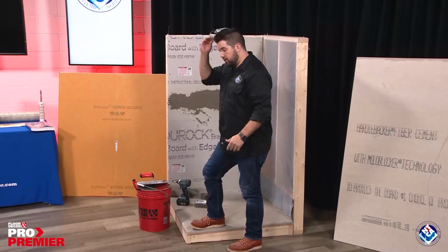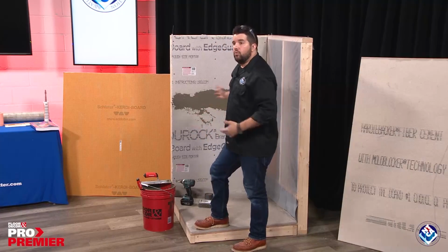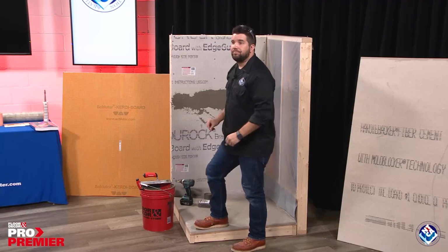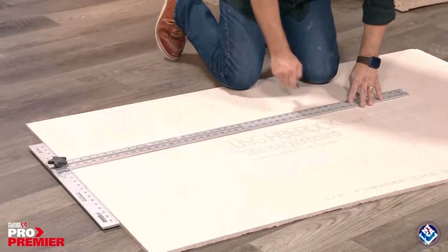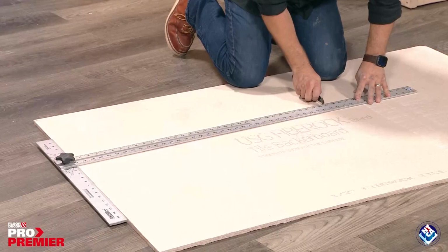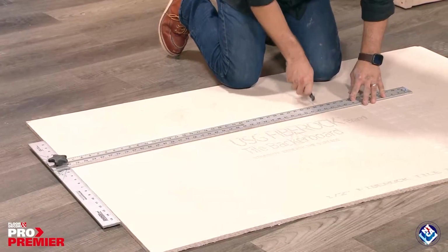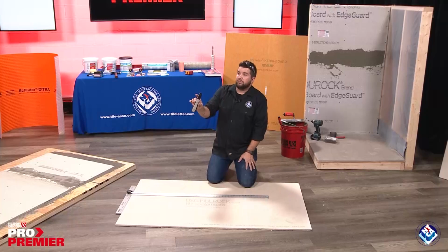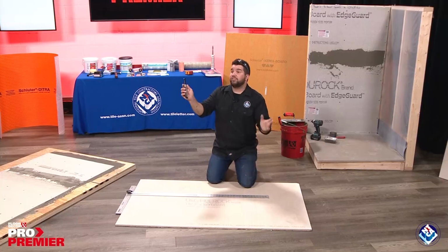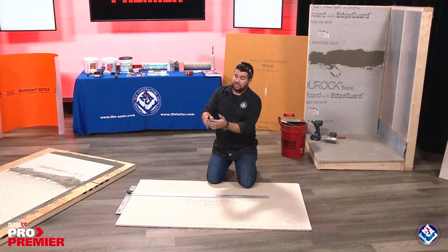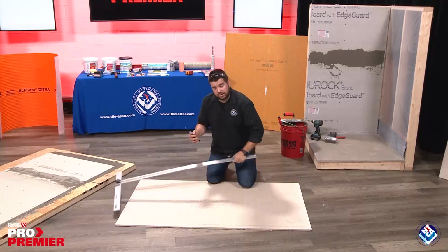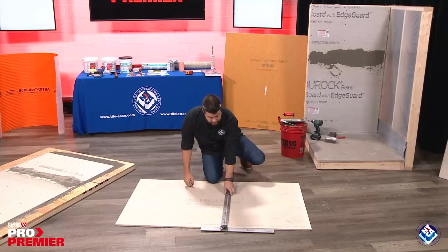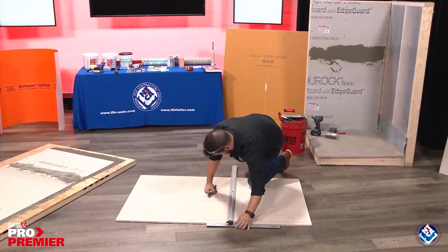So now let's take a look at a fiber cement board, and we're going to actually cut a piece to put on this wall. So I've already measured and we've got 36 inches. And so I'm going to mark, and I'm just using a scoring tool. So this is a scoring tool for cutting cement board. Dust free. That's one of the great benefits, and it's got a sharp tip on it, but it will not cut you. It's not a razor knife. So safe, and effectively it's dust free. So let's line this up.